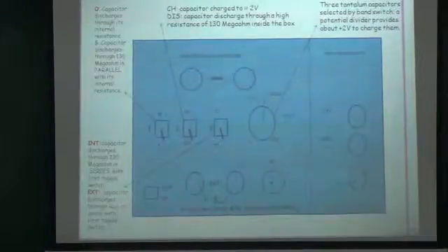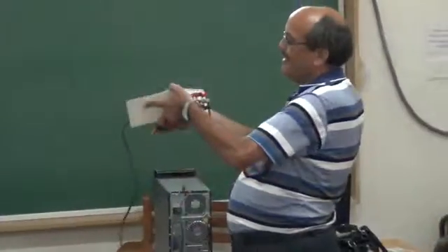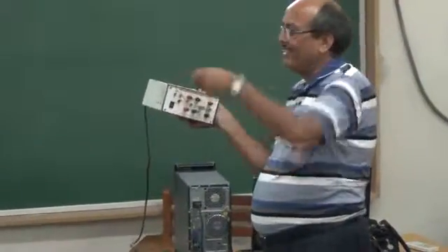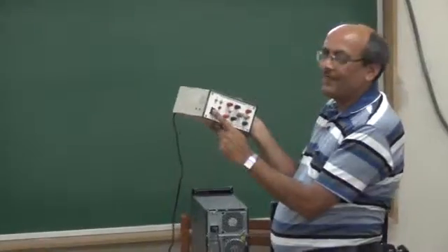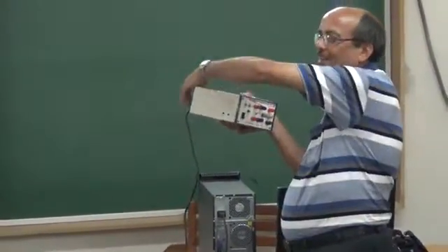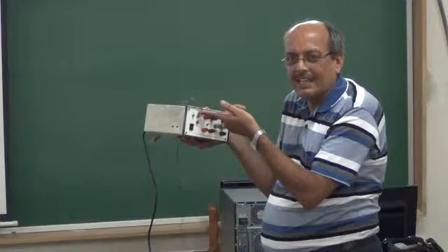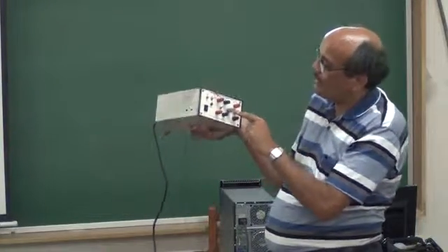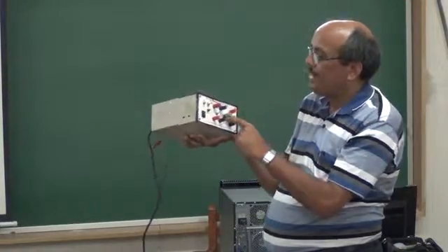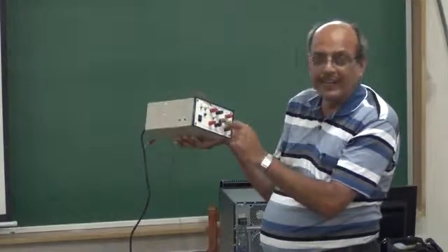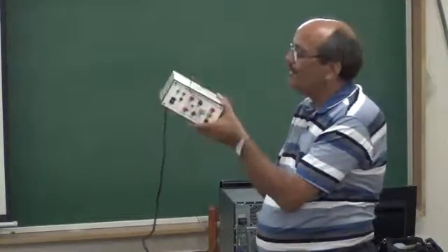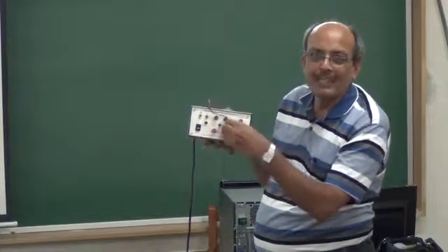This is basically the circuit here. Okay, it's better if I explain it from here. You can see there is a place for the digital multimeter here. So these are the terminals. We have an on-off switch. Then we have the digital multimeter. These are the leads. We have this knob. When you put it up, we can charge the capacitor. Okay, so there are 3 capacitors: 10 microfarad, 47 microfarad, and 100 microfarad. So we can select the knob to the required value of the capacitance.